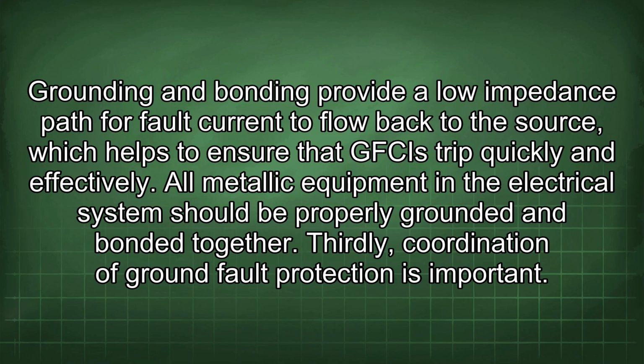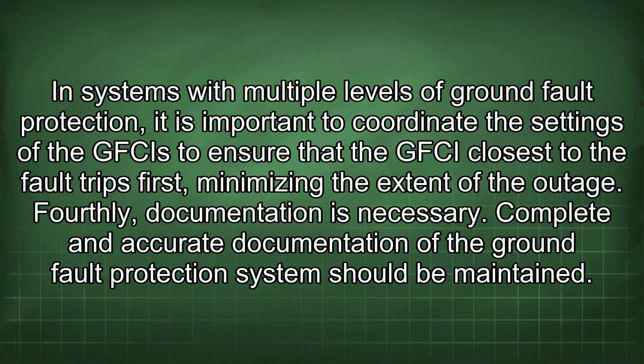Thirdly, coordination of ground fault protection is important. In systems with multiple levels of ground fault protection, it is important to coordinate the settings of the GFCIs to ensure that the GFCI closest to the fault trips first, minimizing the extent of the outage.